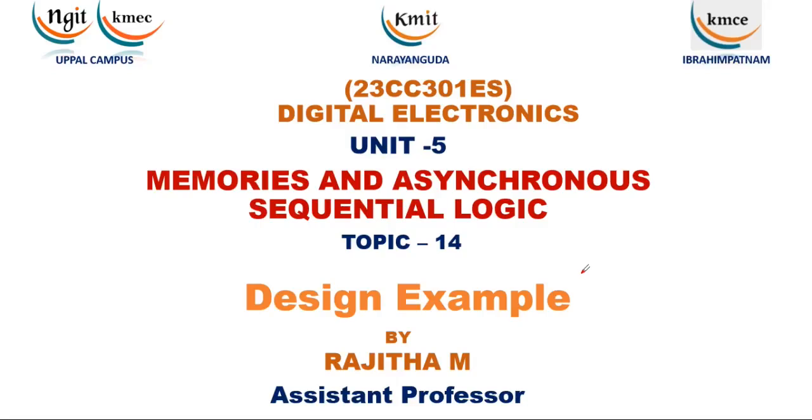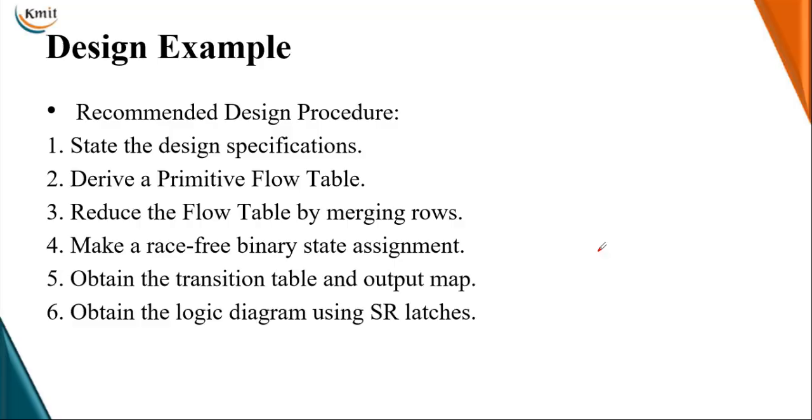Hello all. In today's session, let me practice one more design example in asynchronous sequential circuits. For designing any asynchronous sequential circuit, we have to follow the design procedure. In the design procedure, the first step is to draw the state diagram based on your specifications, and then derive your primitive flow table. After that, we have to reduce the flow table using the merger table. After that, we have to make sure of race-free binary state assignment. Thereafter, we have to see whether any hazards occur or not in the given circuit.